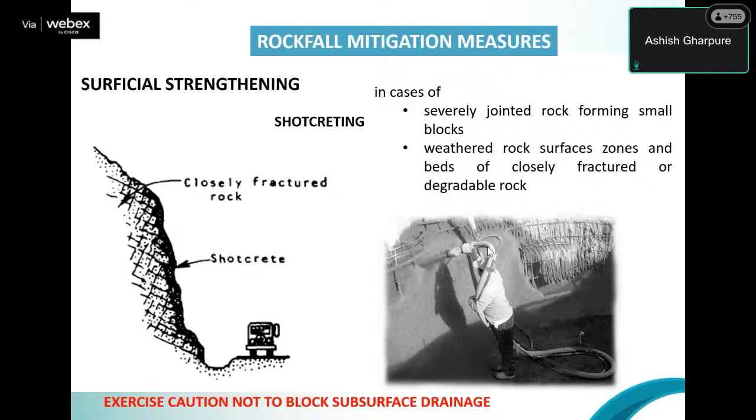So even if shotcrete is given, there is a way to give some drainage details where the water can still be taken out. Otherwise, most of the time, the way we propose, we do not want to block water passage. We want water to pass from every surface safely. That's the whole importance.